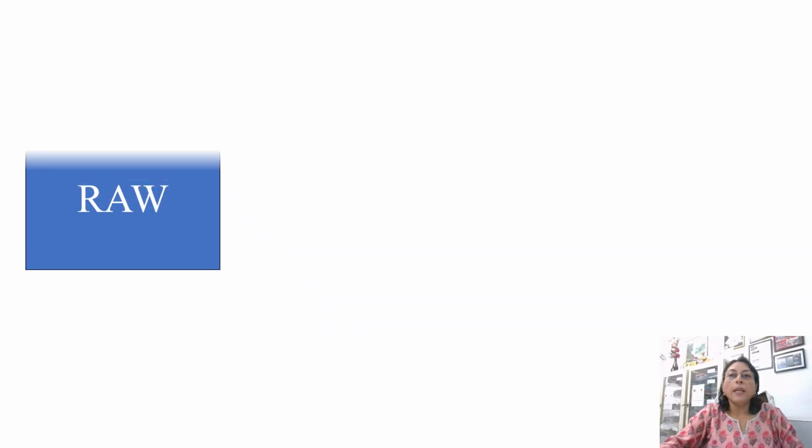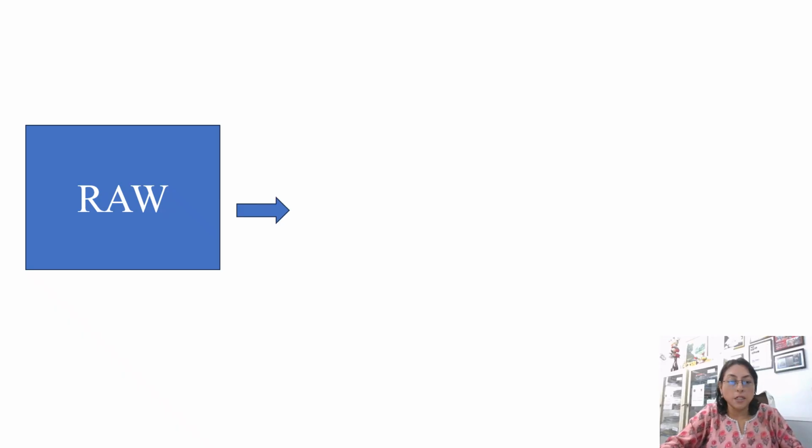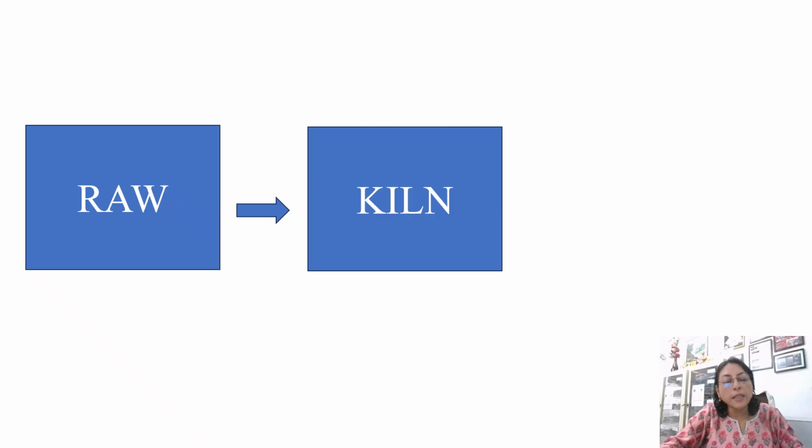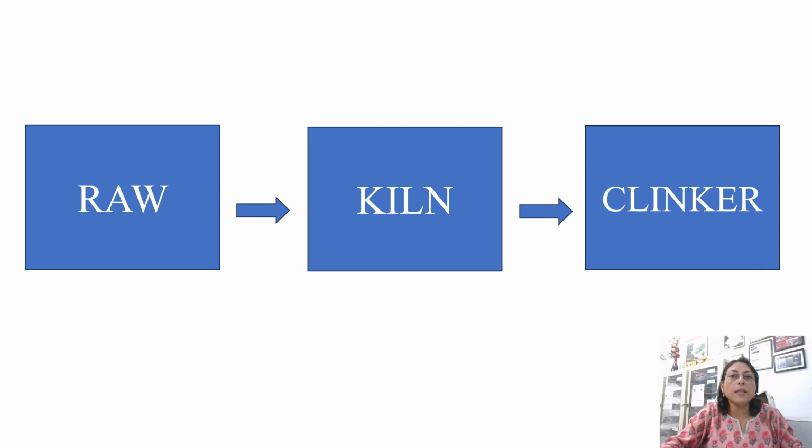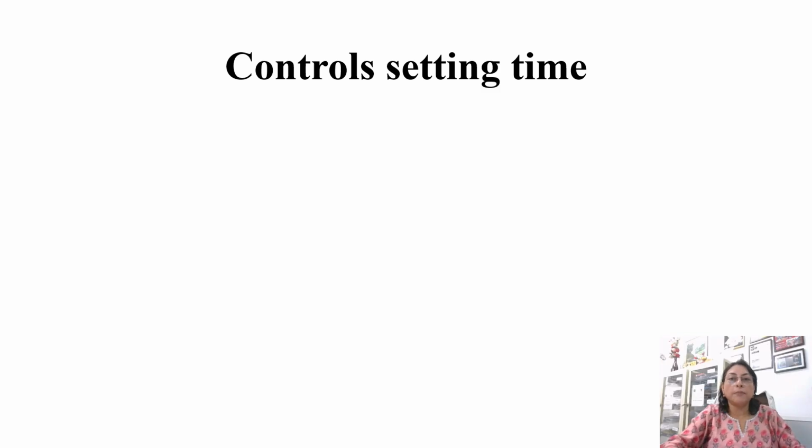The process of making Portland cement is well known, and it can be purchased from any number of manufacturers under various trade names. That is not a problem. But in manufacturing Portland cement, the raw materials are crushed, ground, and proportioned for the desired composition and then blended. The mixture is then fed into a rotary kiln where it is heated to temperatures of up to 1400 to 1650 degrees Celsius. In the process, the mixture is chemically converted to cement clinker, which is subsequently cooled and pulverized.